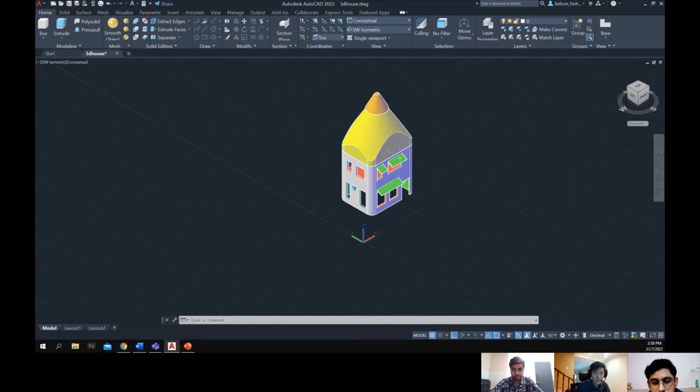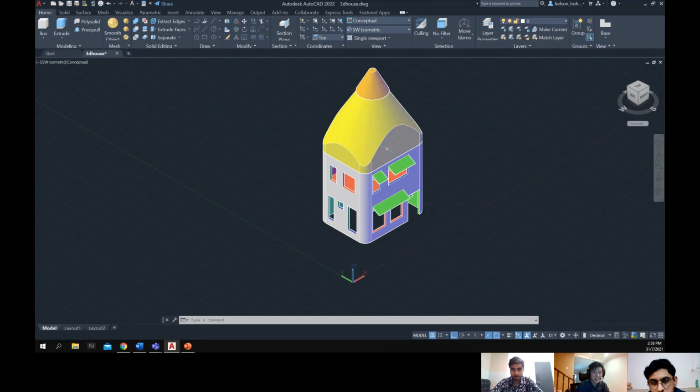To make the structure see-through, I created a smaller rectangle with rounded corners and extruded it, then subtracted it from the bigger one. For the windows, I did the same thing, which is create a rectangle, extrude it and subtract. It's actually very simple. So for the awning, I created a separate entity and just attached it based on the size of the window.